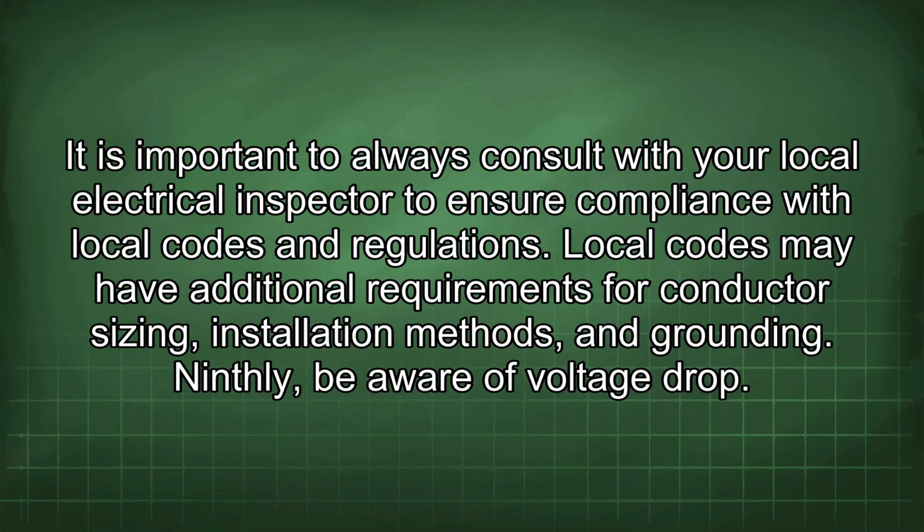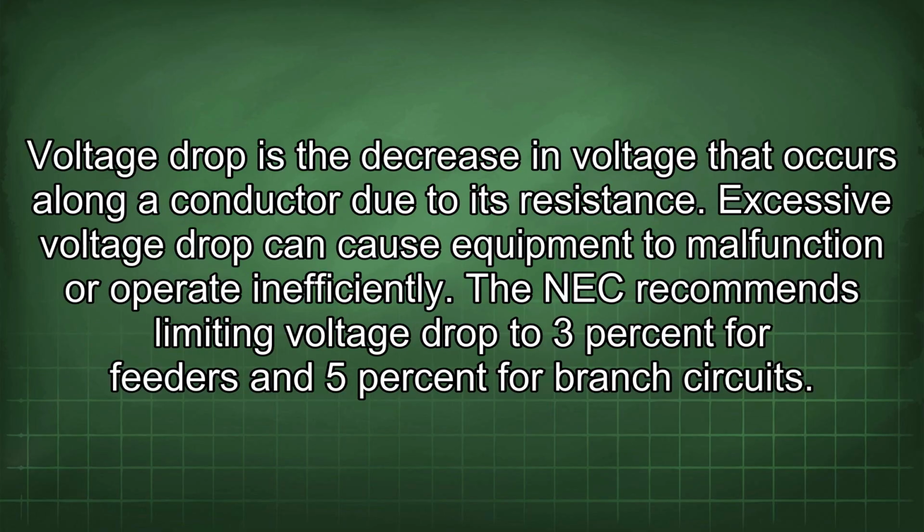Ninthly, be aware of voltage drop. Voltage drop is the decrease in voltage that occurs along a conductor due to its resistance. Excessive voltage drop can cause equipment to malfunction or operate inefficiently. The NEC recommends limiting voltage drop to 3% for feeders and 5% for branch circuits.